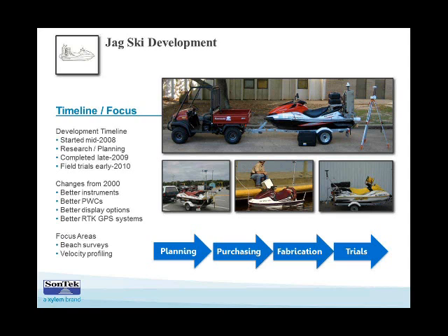And in order to set up the hydrodynamic model, we had a base digital elevation model that would be used to set up the bathymetry for the circulation model. But then we actually needed to do some updating because some of our small tidal channels that we were trying to resolve in the model were too small to pick up by the relatively coarse DEM that we had at the time.